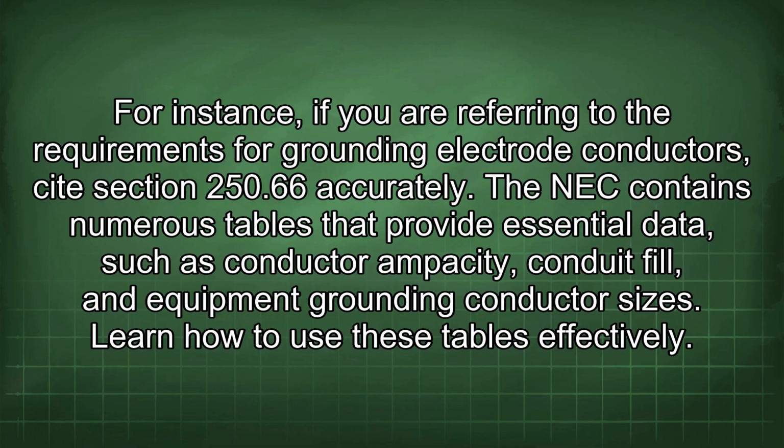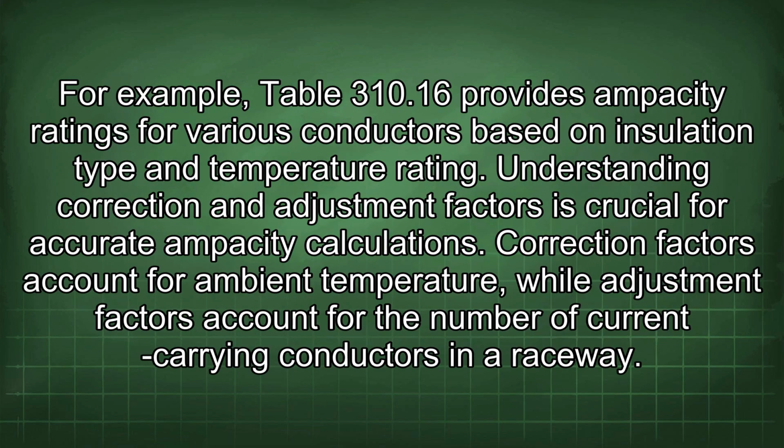The NEC contains numerous tables that provide essential data such as conductor ampacity, conduit fill, and equipment grounding conductor sizes. Learn how to use these tables effectively. For example, Table 310.16 provides ampacity ratings for various conductors based on insulation type and temperature rating.